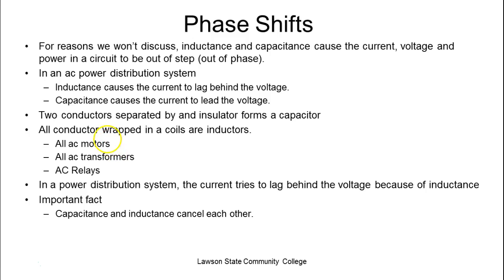So these are very, very important. And by the way, if the capacitor goes out, the motor will sit there and hum. It can't start up because it doesn't see a phase shift. 3 phases creates a rotating magnetic field. So this is one big advantage of a 3-phase motor over a single-phase motor.